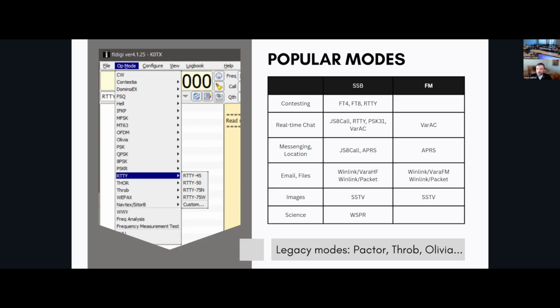So you can interoperate between the radios that have that internally and your regular radio that is not APRS capable, but by adding a sound card and a computer, you can make it APRS capable. What that will allow you is to report your positioning, which can be tracked through the internet if you want, and it will allow you to exchange messages, basically like a chat, but it will wait for the station to receive the messages. It doesn't have to be real time.